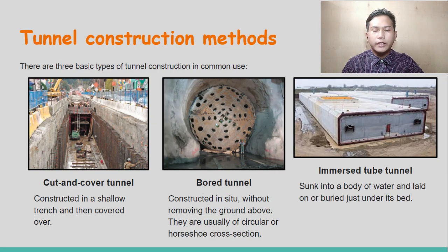How to build the tunnel system? There are various kinds of methods that are used to build the tunnel. However, I will just list down the main or basic types of tunnel construction methods that are commonly used. So the first one is the cut and cover tunnel method. Basically, it is constructed in a shallow trench and it will be covered over after digging the trench.